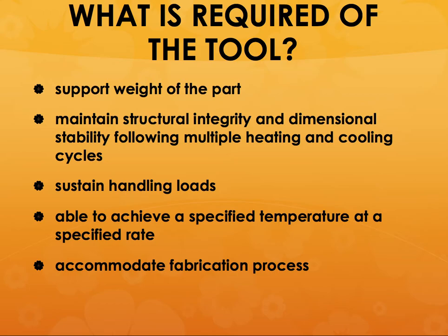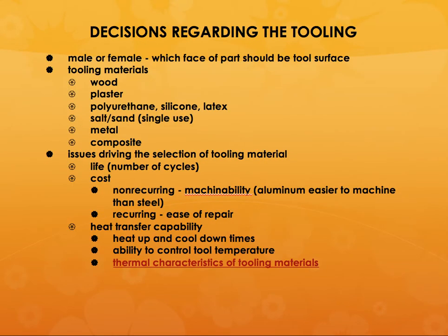These tooling materials are going to be exposed to high temperatures and high pressures, and the tooling has to accommodate the fabrication process. So what are the decisions? Whether it is male or female, which face of the part should be the tool surface, what kind of tooling materials are used, and what is the lifetime, what is the cost, what is the non-recurring cost of it,